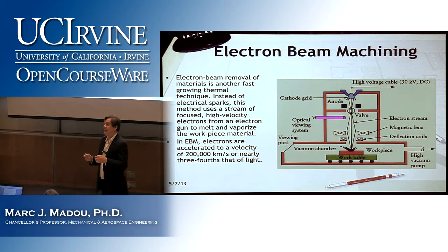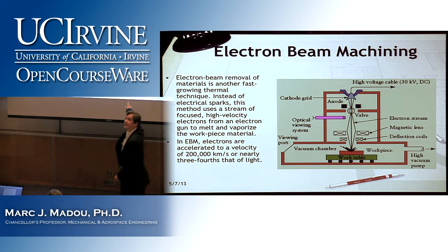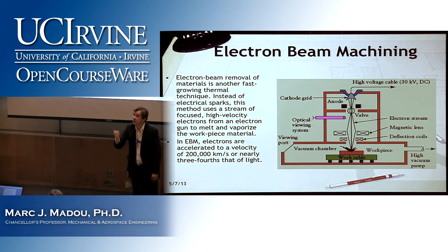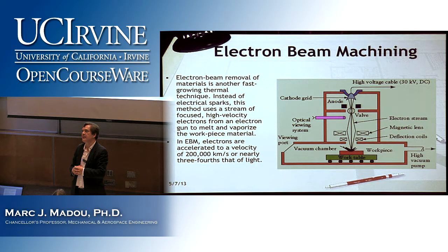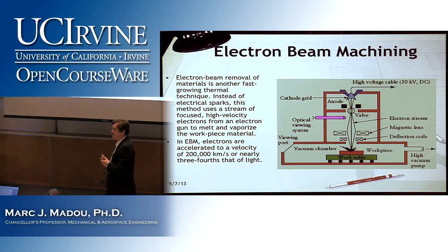But you might have heard that in 3D printing, more and more people now are starting to look at E-beam machines to solidify particles. So this is subtractive. Huh? I'm cutting with my E-beam. But you can also have a bed of a metal powder, and where the electron beam hits the metal powder, it can melt it and solidify it together. And so now there's actually more interest in looking at E-beam as a very powerful tool that can do both subtractive and additive. Right? And in the context of this 3D printing, this is getting kind of a second wind. And maybe people will be able to reduce the cost of this machinery.